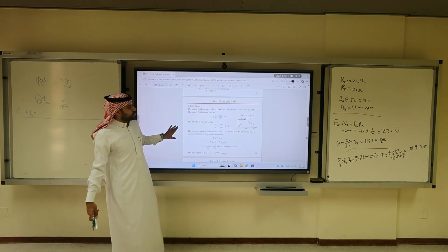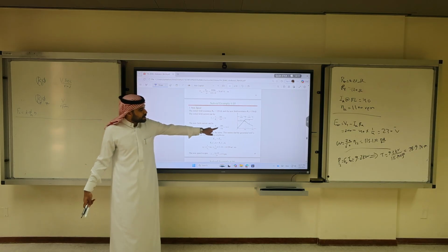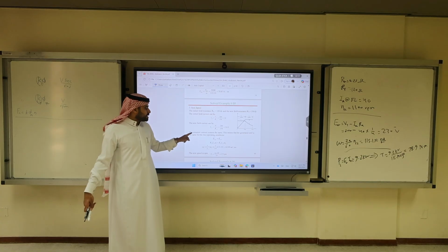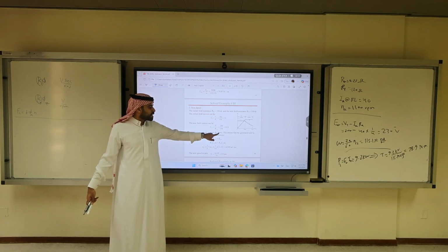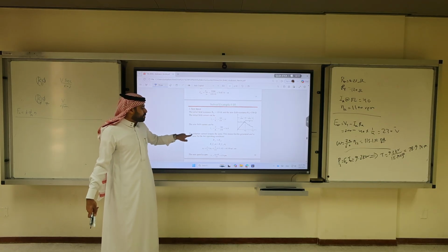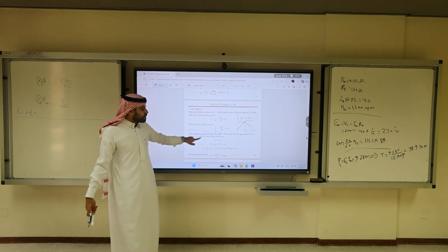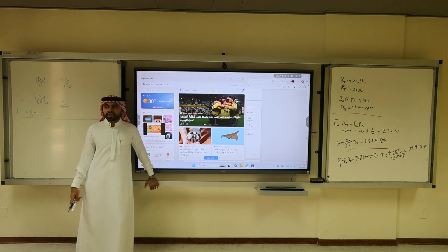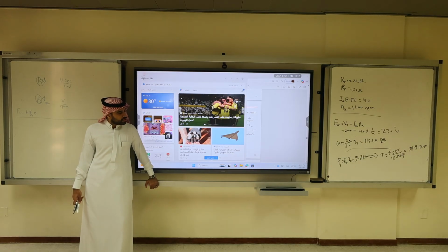No, that's not the right way to do it. So get the field current, it will be smaller. So EA, why did he say, oh, because the armature current is the same. Because the armature current is the same, both EAs are the same. The armature current is still 40.